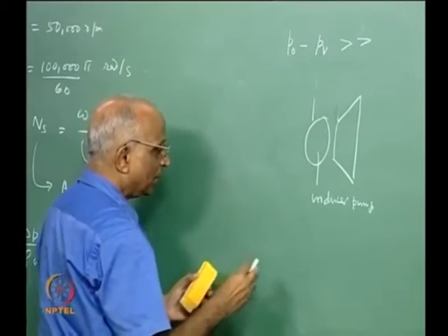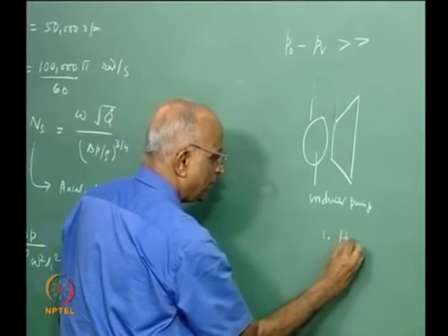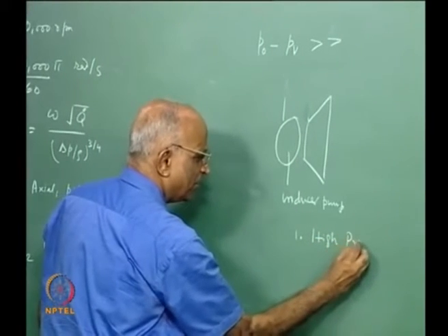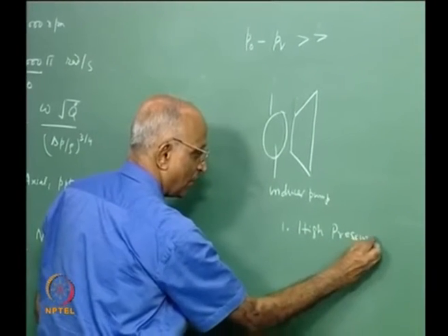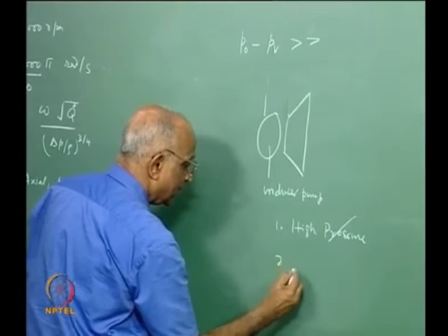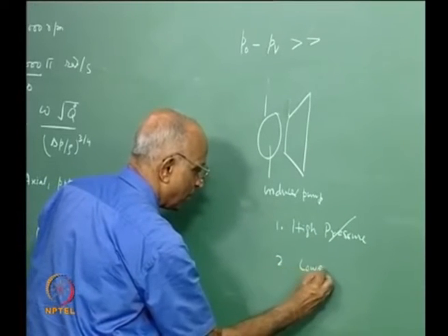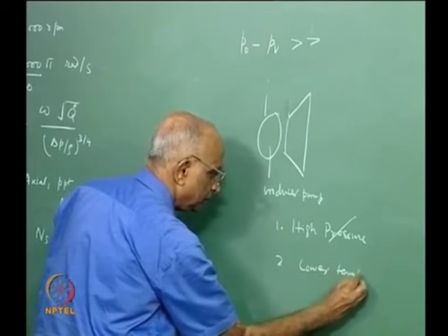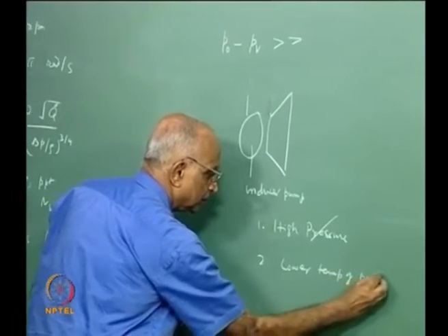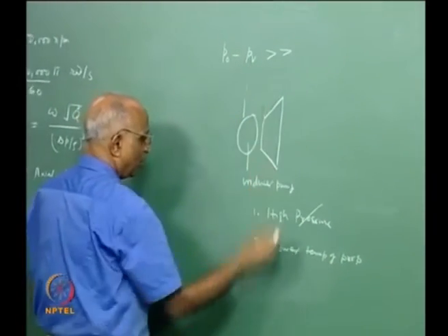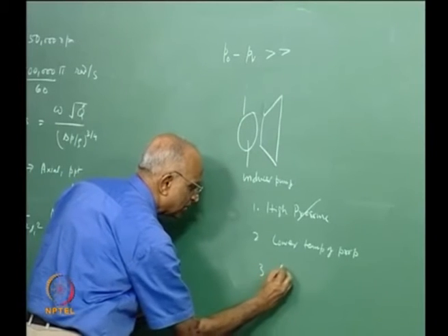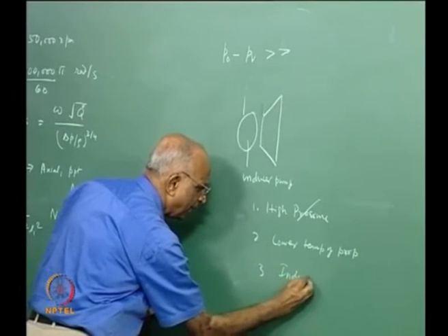by the following three: either provide high pressure tankages, which is not the correct solution, which is not possible. Second is lower the temperature of the propellants, in which case I reduce the value of PV, or I put something like an inducer ahead of the main pump.